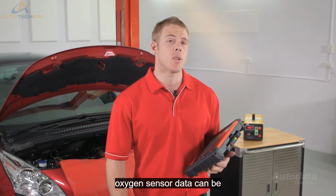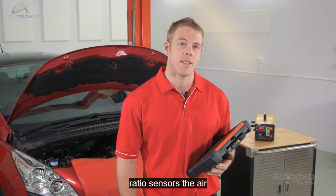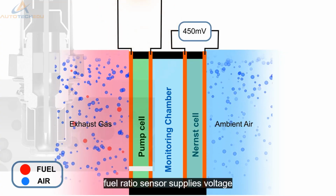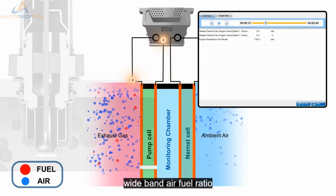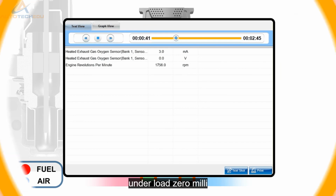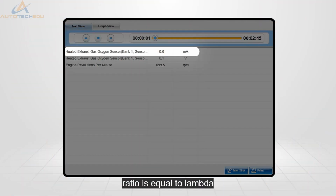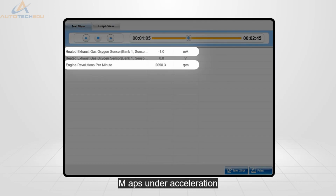Oxygen sensor data can be tricky to interpret, especially if you haven't had much experience with wideband air-fuel ratio sensors. The air-fuel ratio sensor supplies voltage and pump current data to the ECM. This is a correctly functioning wideband air-fuel ratio sensor operating at idle and under load. 0 milliamps indicates the air-fuel ratio is equal to lambda, while a negative reading indicates a rich mixture with a positive being lean. At idle, the reading will be 0 milliamps. Under acceleration, we should see the value produce a negative current flow, and on deceleration, we would have a positive current flow.